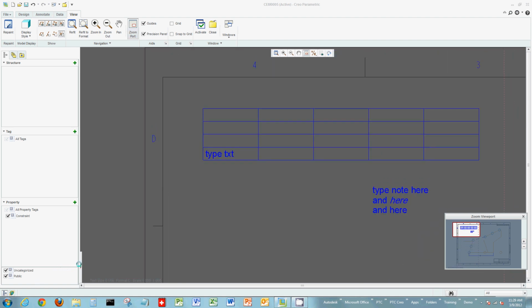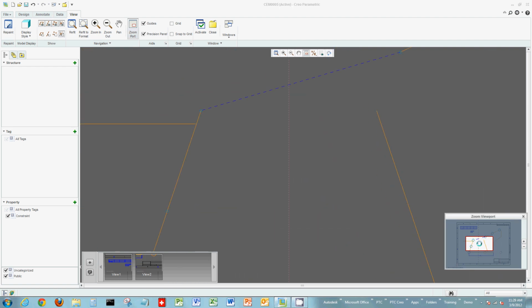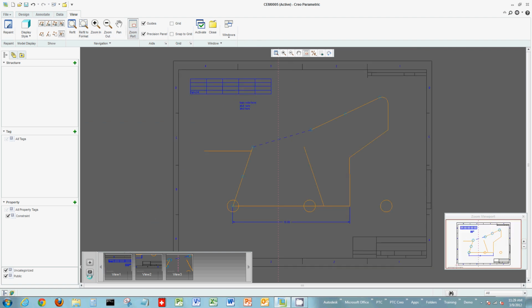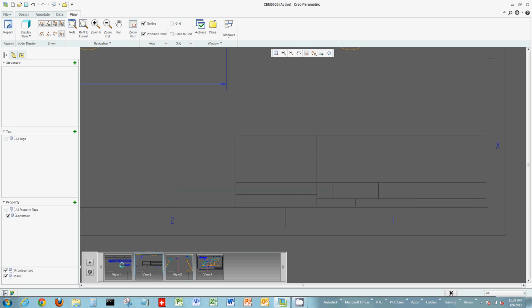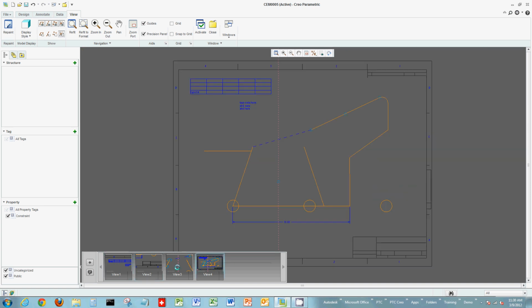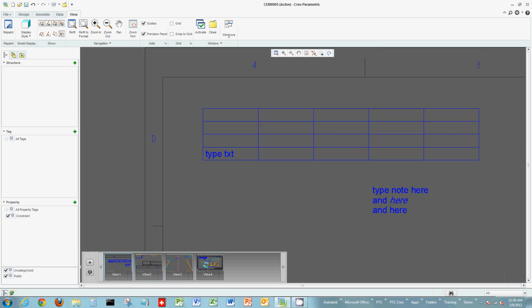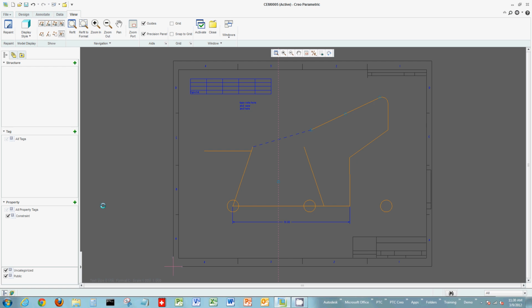Now you can also use, in this case, little snapshots. So maybe I'd like to take a snapshot of this current position. Maybe I'll move down to the lower right, take a snapshot of it. Maybe I'll move into the middle, take a snapshot of it. And finally what I'll do is I'm going to refit and then take a snapshot of that window. And now the snapshots in this case on the bottom, these little views, allow me to actually quickly go back and forth to zooms. They're actually called zoom views. So I can zoom to these views of what I just took a little photograph of, or a snapshot, and then I can minimize that actual part of the screen.